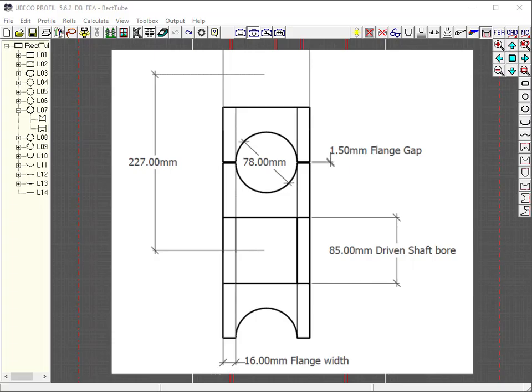In order to completely surround the closed section, as in sizing a round welded tube, the driven roll contours are created in the same way as tools for roll form sections, except where the outer flanges of the tools meet one another. Here we will use another feature of profile design to create flange gaps between the roll tool faces.